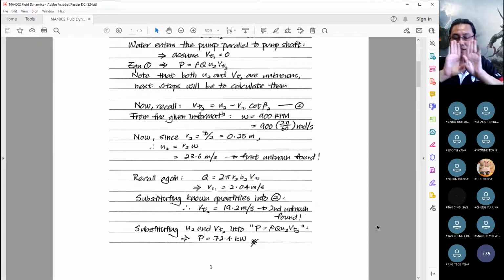Okay, that's going to give you the cylindrical surface area. And then if you multiply by the Vm, the normal velocity component that's coming out from this cylindrical surface, surely it must be equal to the flow rate. It's a bit like potential flow, isn't it? It's a bit like a source, except that in this case we have got a blade height, if you think about it. In fact, that's the only difference, right?